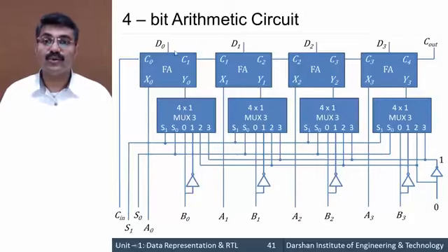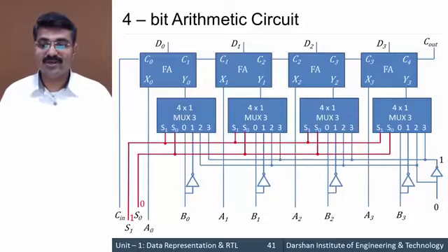Now we are supposed to see how it works, so let us take an example. Let us take the values of S1 and S0 to be 1, 0 respectively. So S1 is 1, S0 is 0. You know the working of a multiplexer. As per S1 and S0 being 1, 0, the second line would be selected, because the corresponding decimal value is 2, and on input line 2 we have the value 0.